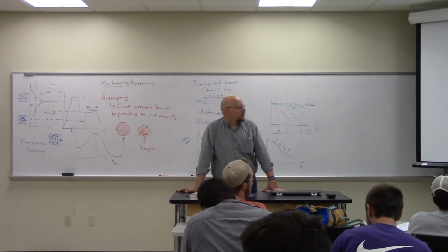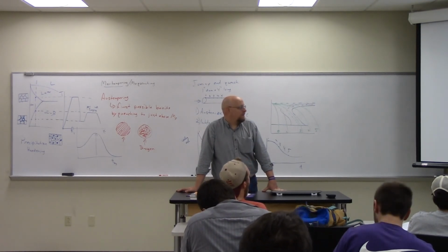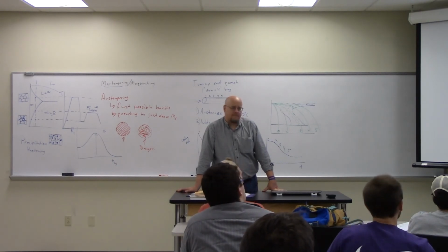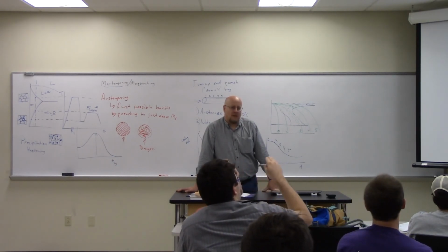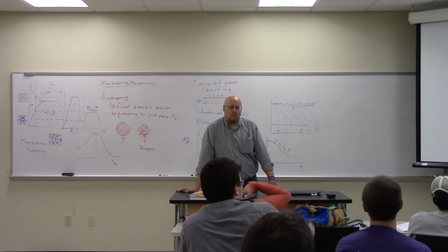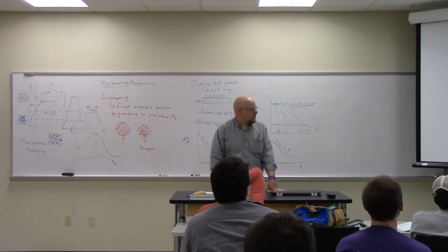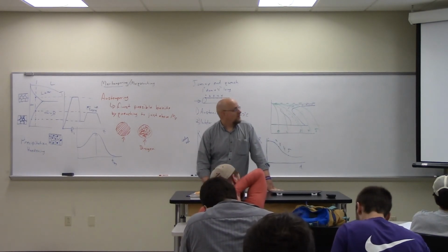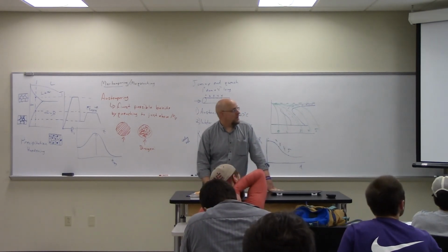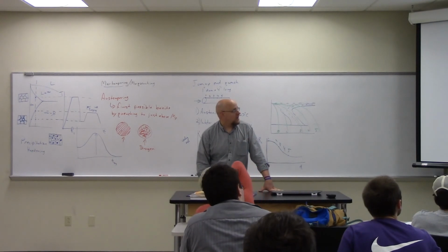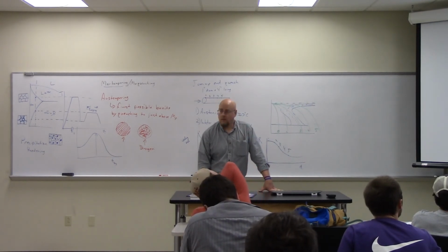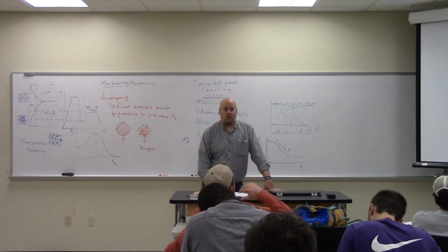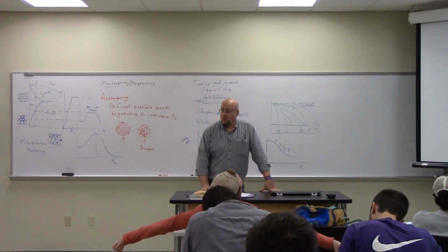So for part D, what do you think that curve is going to look like? It's going to go more quickly, right? Where does it say? I don't see a time. For steady state, repeat A through C for a steady rate of cooling in exactly 1 minute, as opposed to 1 day. I see. Okay? So now we're quenching from 727 to 200 in a minute.